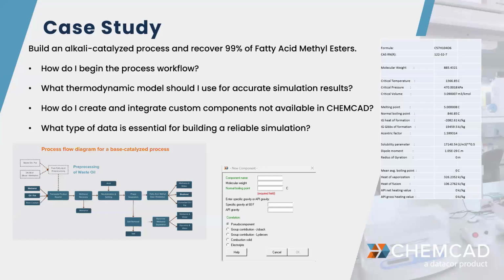Also, in the biodiesel process, at some point you will get a liquid-liquid approach, so in those cases, probably modified UNIFAC will be a good option to predict those two liquid phases and the activity coefficient interactions between the methanol and the oil, and the glycerol and the oil.